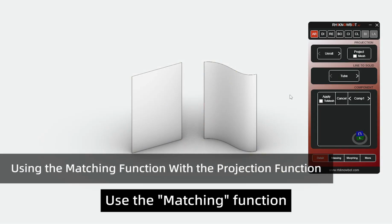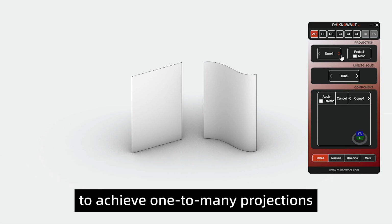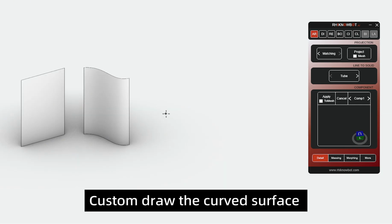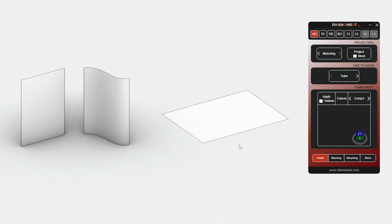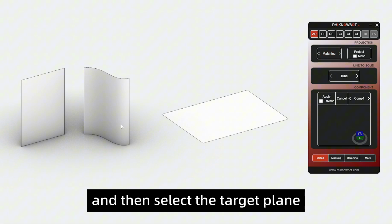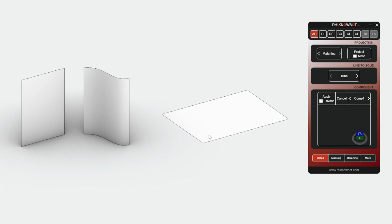Use the matching function to achieve one-to-many projections. Switch to the matching function. Custom draw the curved surface. Click Matching to select the reference plane, and then select the target plane.